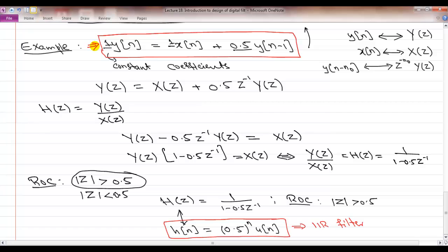Okay. So what do I have to do to implement this filter? All I do is, in hardware, I save my sample of the previous output. And every time a new input comes in, I simply add that to the previous output with a factor of 0.5, and I have my filter implemented. In an IIR filter, I'm not going to use the convolution formula. What I'm going to use is turn it into a difference equation, and then I can easily implement it.